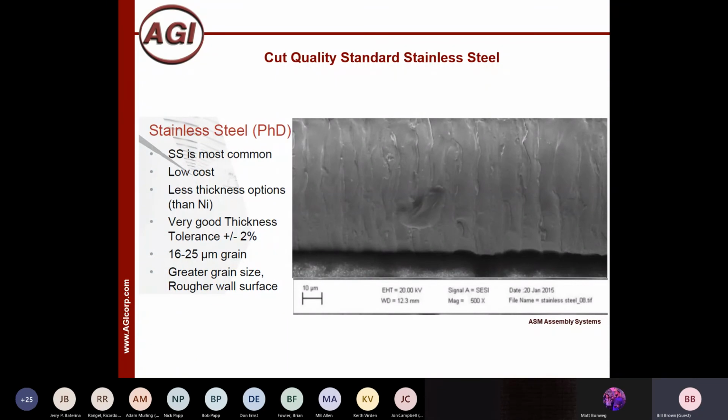So there's a lot of surface area for your paste to stick to, and rough edges because of that grain size. The only option was to send it out to be electropolished, and that removed some of those burrs and other defects in the material on the aperture wall.